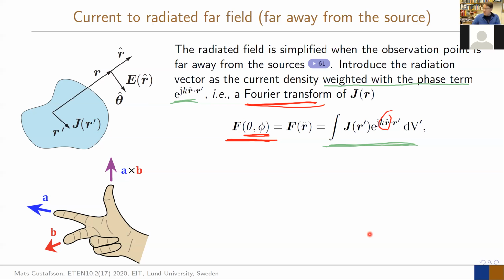But it means that you have your antenna here. And what you say is, how does this antenna radiate in this direction? How does it radiate in this direction? How does it radiate in this direction? The direction is this theta and phi. And the current is going on this dipole, and you want to know how it radiates its power. That is given by this radiation vector, of course. The radiation vector gives the E field, and then the square of the E field gives the power that becomes radiated. So these are the quantities that we have.